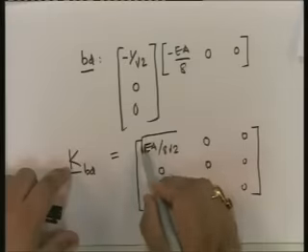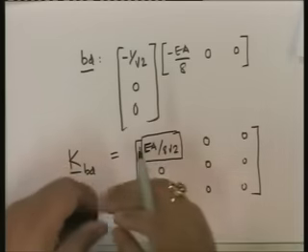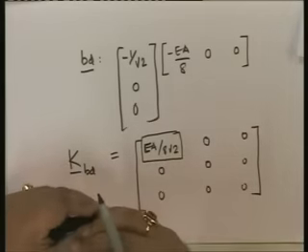In fact, the bracing member is only provided to provide additional rigidity against lateral displacement. That is the whole purpose of the bracing member. It is not there to take vertical loads. It's there to provide, when there's lateral displacement, and therefore it is not surprising that it adds to this. Okay.